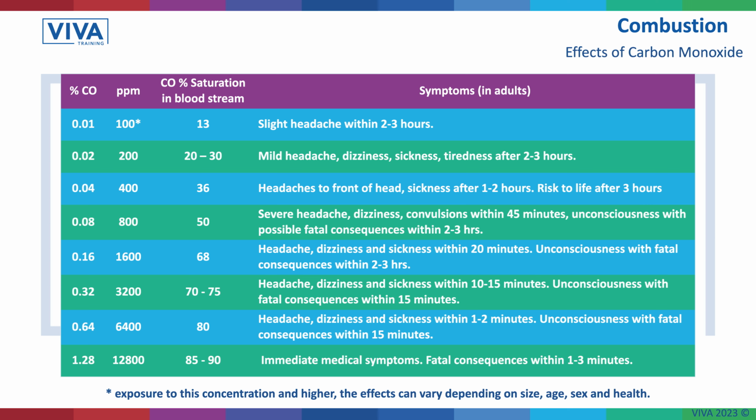6,400 parts per million, 80% saturation, headaches, dizziness, sickness in 1 or 2 minutes, very short period of time, unconscious, fatal results, 15 minutes. And the last one, 12,800, 85 to 90% saturation, immediate medical symptoms. If you walked into a room with that saturation in there, you might not smell the CO, but you're going to be affected literally straight away, fatal within 1 to 3 minutes.